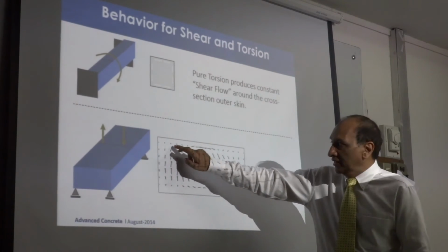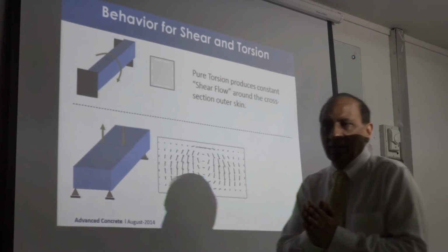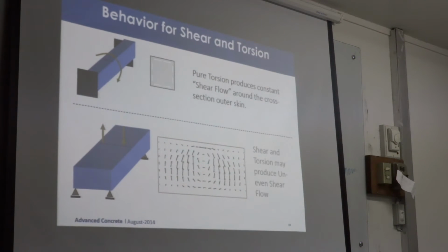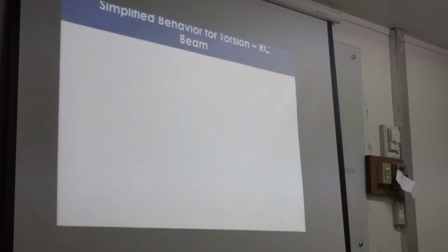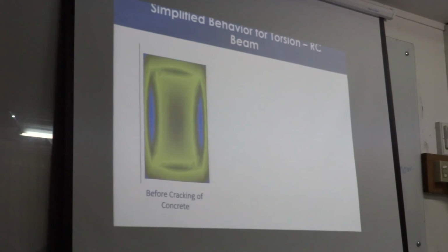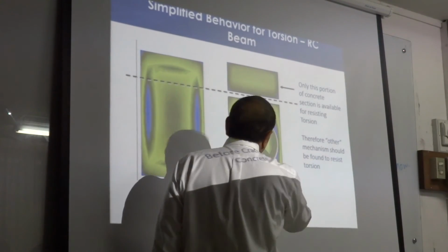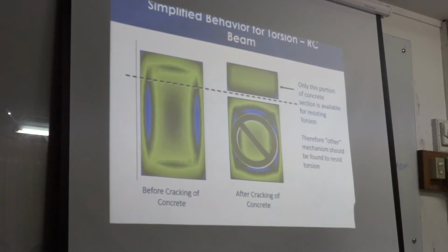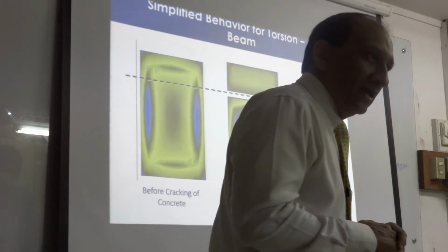So far we have been just talking about top and bottom being rebars, right? And we said, well, we have to. But actually there are 6 actions, and there are a lot of reinforcement coming from those actions, and they could all be interacting with each other. Same reinforcement serving many purposes. For example, this bar could be a tension bar for moment, could be a compression bar for axial compression, could be a tension bar for tension, could be a longitudinal bar for torsion, or could be a compression bar for another moment direction. Or if the moment direction changes, same bar could be a compression bar or could be a tension bar, right? So that means it is quite hard to really find out the amount of each rebar and what it is doing. How much of the bar is going for compression, how much the bar is going for bending, how much the bar is going for torsion, right? Same bar here, so it has many functions.